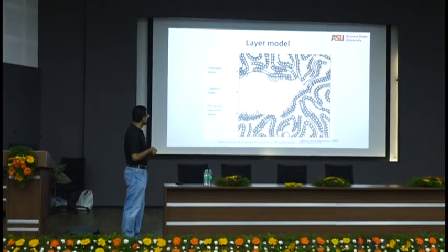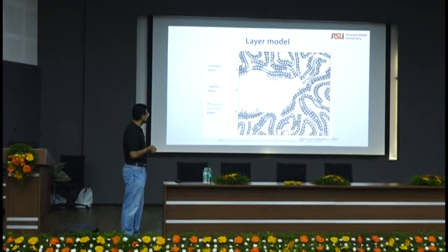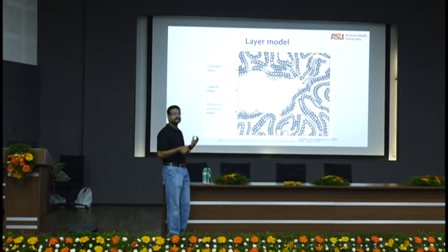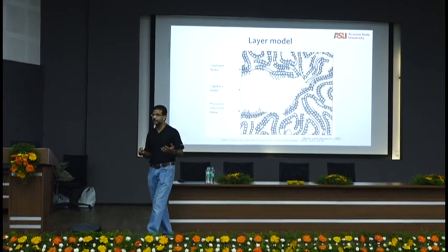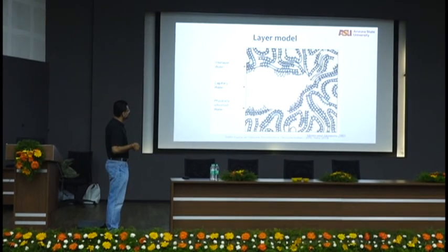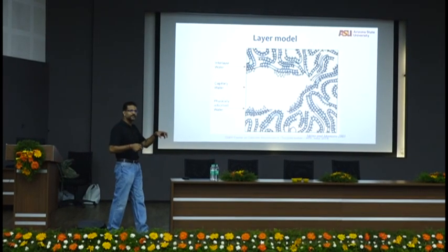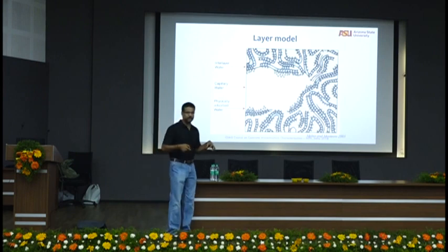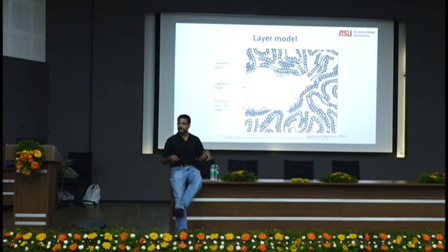So you have layers, you have water in between the CSH gel. Water in between the layers is called the interlayer water. The water that's adsorbed on the surfaces is held onto the surfaces by a theory of adsorption. Have you heard of the BET theory? Brunauer, Emmett, Teller, BET. I'll show you some BET theory issues.